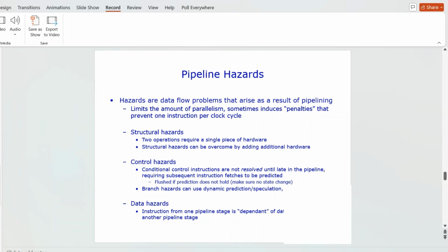So if the branch will be taken, the instruction that is already fetched will be flushed, and a new instruction will be brought from the instruction memory. So it also wastes pipeline cycle time. That's why it is called a control hazard. And the solution techniques are prediction of branch and reshuffling of instructions, so that the branch decision gets some time.